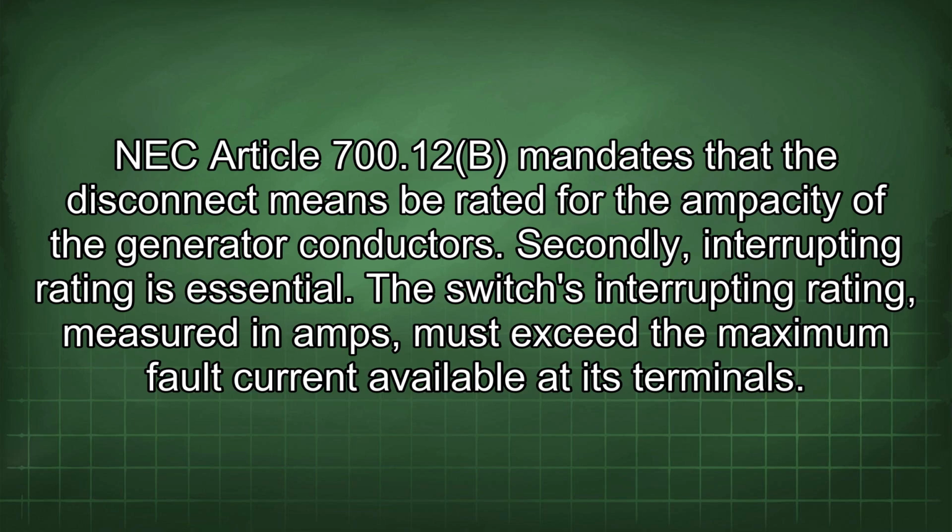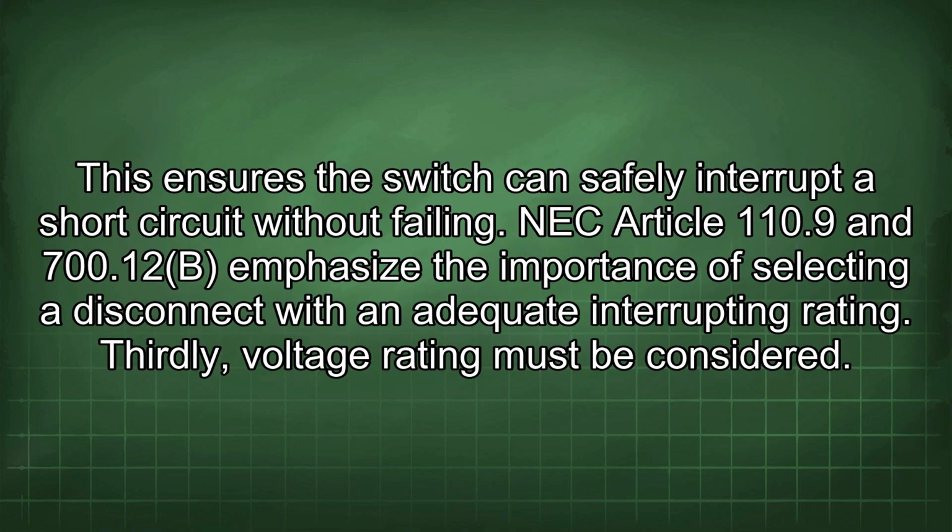Secondly, interrupting rating is essential. The switch's interrupting rating, measured in amps, must exceed the maximum fault current available at its terminals. This ensures the switch can safely interrupt a short circuit without failing. NEC Article 110.9 and 700.12b emphasize the importance of selecting a disconnect with an adequate interrupting rating.